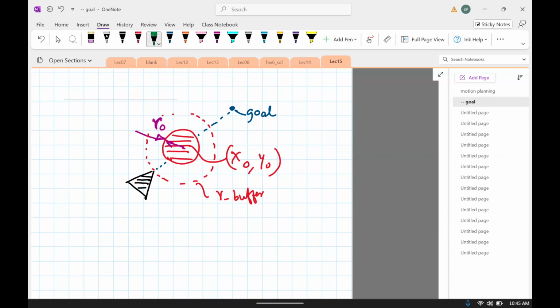And the simplest way to do it is to just say, I'm going to turn 90 degrees to this line. So if I turn 90 degrees, then I'm just going to go away from the obstacle. And there's some assumption about the obstacle. It's basically a convex obstacle. Convex means the shape is like it's shown there. Concave would be like this. If it was concave, that would be trouble, right? It would be difficult, but we assume it to be convex. In fact, we'll only stick with circles. So we know that doing a 90 degree turn, either left side or right side, will work. So you could just randomly choose left or right. If you do that, you're good.